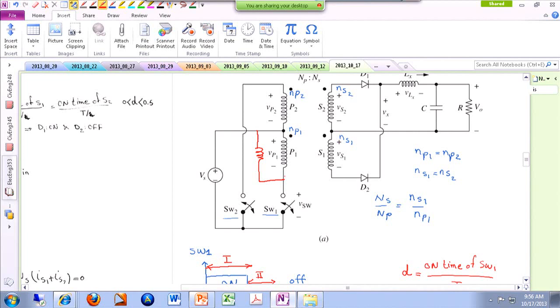So in order to make things simpler, we assume that this magnetizing inductance does not exist. But in the end, we have to make sure that the voltage that we are applying over here does not have any DC bias, or in other words, on average, it's 0. If we satisfy that condition, the fact that we have neglected the magnetizing inductance doesn't really hurt us, and it is never going to get saturated.